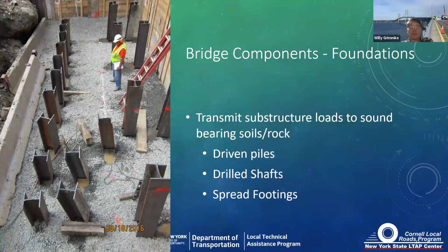The other deep foundation option that's sometimes used, depending on soil condition, are drilled shafts. In areas where there is rock close to the surface, sometimes we will place spread footings on rock, if we're crossing a waterway and there's not a risk of scour or undermining, or if we're crossing something where there's no real water flow, like a highway, we will sometimes have spread footings if the soils beneath are firm enough to support the bridge loads without settlement.